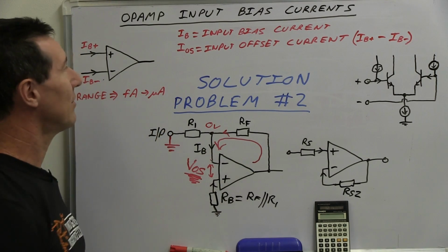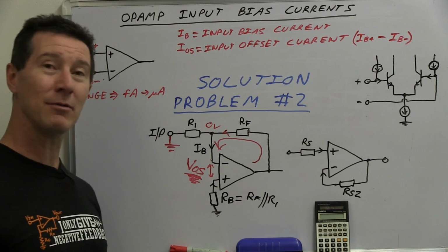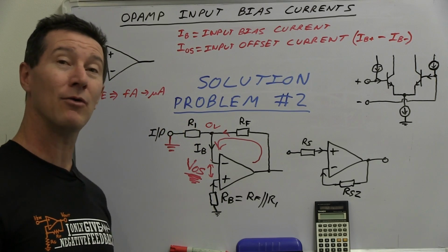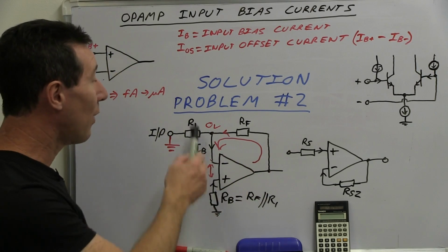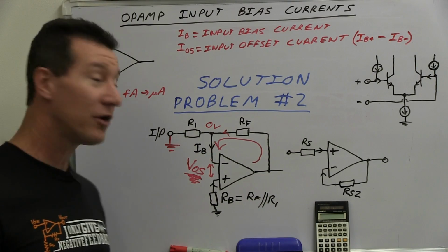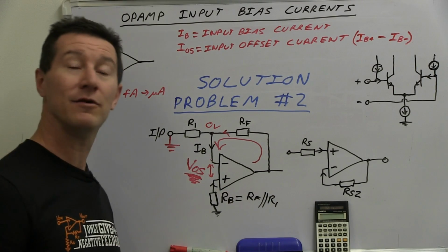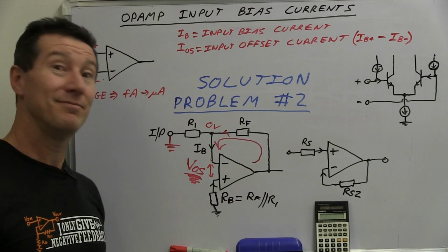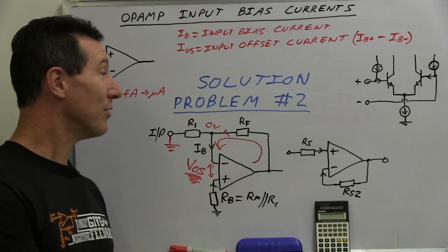So there's actually two parameters there that you have to look at. Not only the input bias current itself, which could be really low, it might be 10 picoamps, for example. But then if your IOS is 100 picoamps, for example, then, well, geez, it's all over the shop. There's no way that you can choose a resistor bias value that's going to work. You might fluke it. You might be able to tweak it for an individual chip or an individual circuit, but just choosing a generic value to do it, no, you're not going to be able to do it.